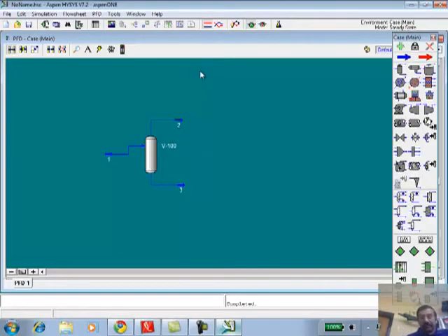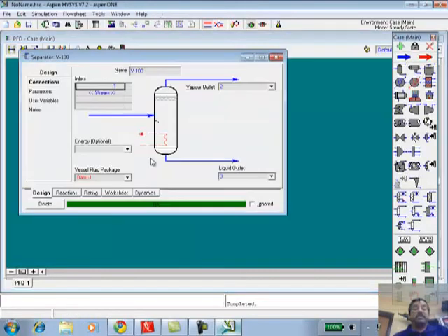So if we change a value of the parameters of the system, they automatically adjust the rest of them to fit. Exactly. How can we make it hold certain values constant, as a defined constant, instead of changing? So we'll change other variables. That's more sophisticated. It's a good question. It is possible to do because that is the kind of tool that you need. Because you might say, I don't want to do a trial and error tracking 100 temperatures, but I know that I want the propane composition to be a certain value. So what you're doing effectively is saying, I want to transfer the degree of freedom to one of the outputs. I want to fix the propane composition to be 0.15. Find me the temperature and pressure that will do that.